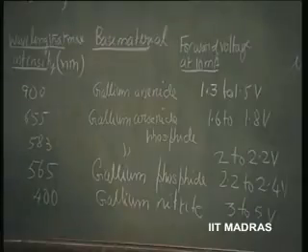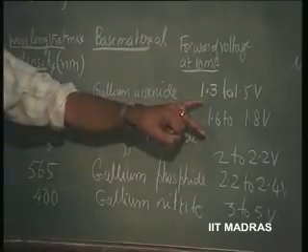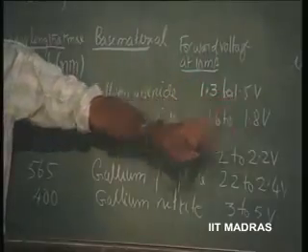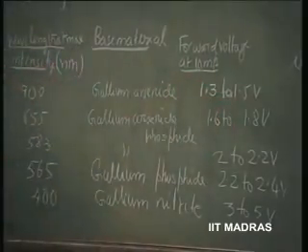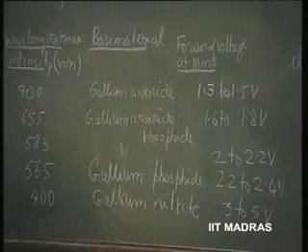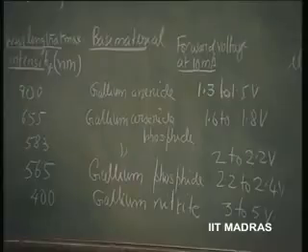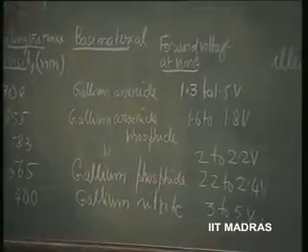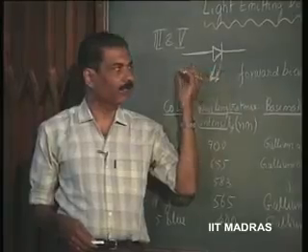Gradually it might become 0.8 to 1 as it goes to higher currents, but here it is greater than 1, for 10 milliamperes itself 1.5 volts. These typical values you should know in order to bias these so that they can emit sufficient intensity of light. So the light intensity obviously depends upon the magnitude of current flowing through it.